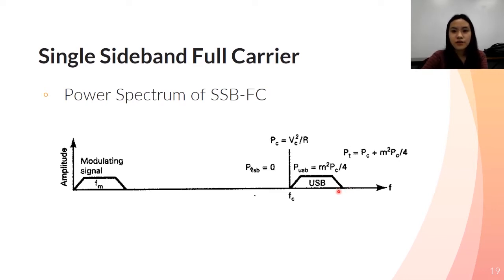For conventional double sideband AM with 100% modulation, 2/3 of the total transmitted power is in the carrier and 1/3 is in the sideband. Therefore, although single sideband full carrier requires less total power, it actually utilizes a small percentage of that power for the information carrying portion of the signal.